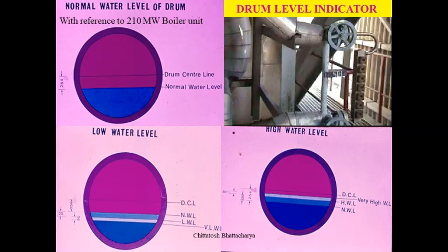We also have Hydrastep. Hydrastep gives us remote liquid level indicators, and in general there are annunciations or alarms for low levels, very low levels, high levels and very high levels.